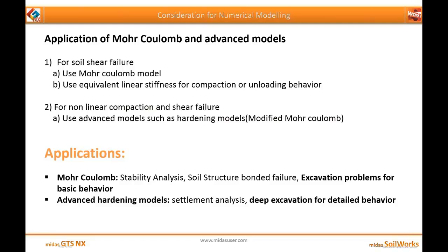Whenever you want to consider soil shear failure, one should consider Mohr-Coulomb, which uses an equivalent linear stiffness for compaction or unloading behavior. If you want to consider nonlinear compaction and shear failure, you have to use advanced models such as the hardening models, which include modified Mohr-Coulomb and modified Cam-Clay models.